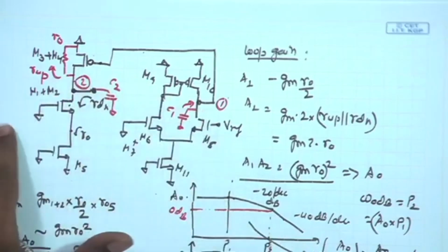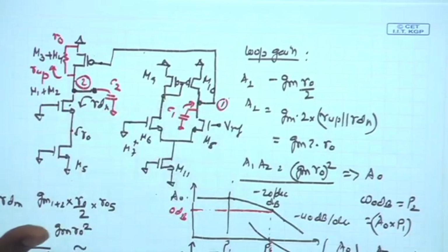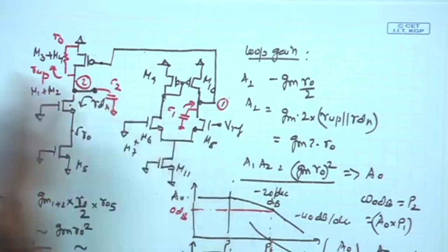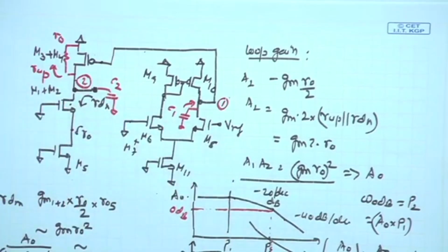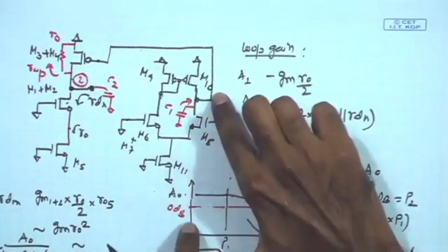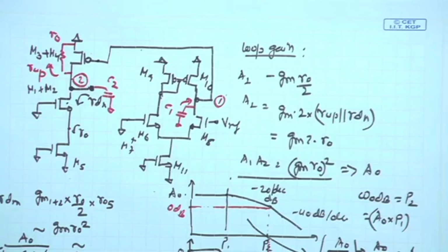As we have seen earlier, one of the common methods to achieve such splitting of poles, or pushing of one of the critical poles towards low frequency, is the Miller effect. So, we can intentionally add a capacitance between two circuit nodes, so that at one of the circuit nodes the overall capacitance, because of the Miller multiplication, becomes very high, and as a result the pole at that particular node is pushed to very low frequency.